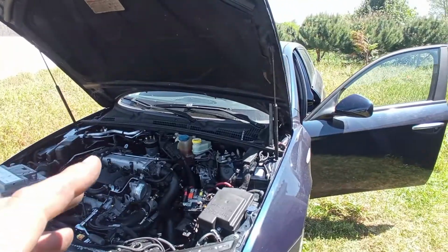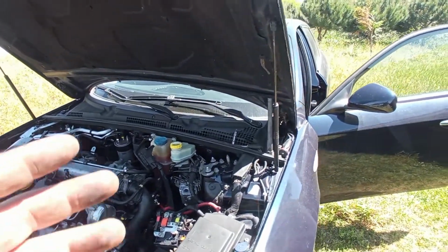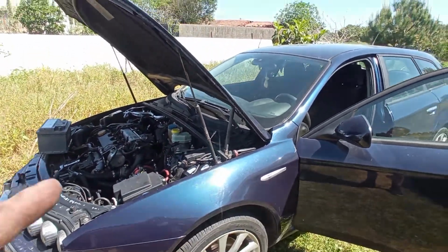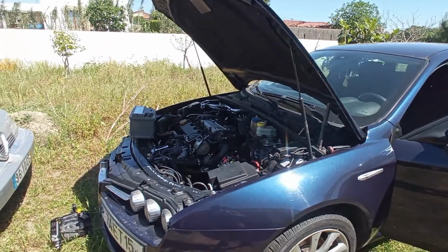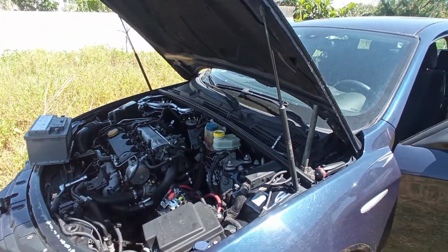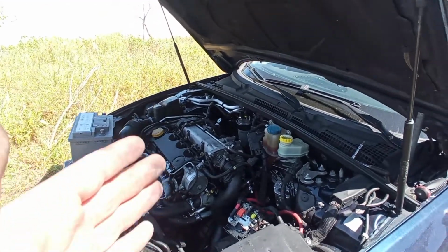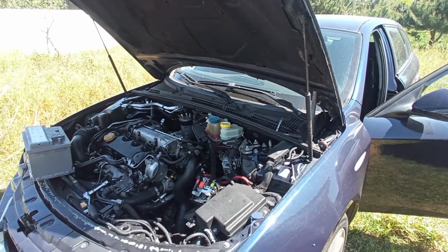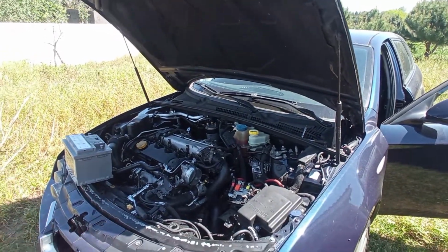And before starting the car, we want to reconnect our diagnosis machine to see some things about the DPF, but before that, to reset some parameters about the engine. Okay, I want to say to the engine that I have a new throttle body. I want to say to the engine that I have new components, even though some of them are not really new. It has to have a clean slate to start with.